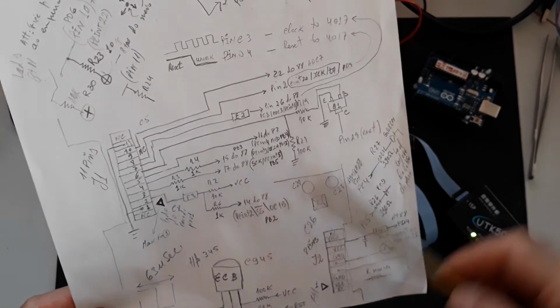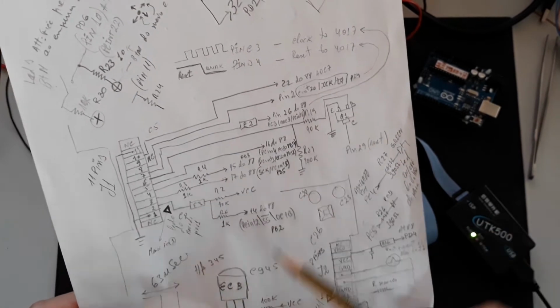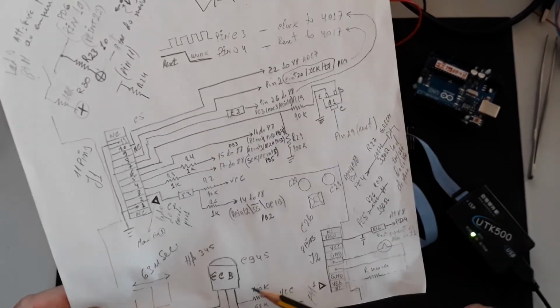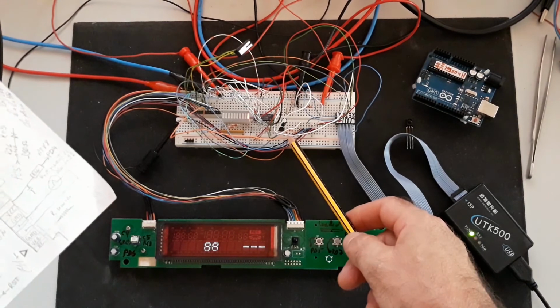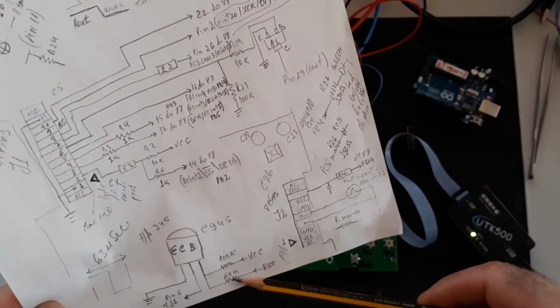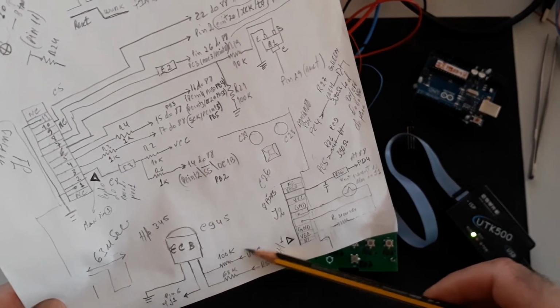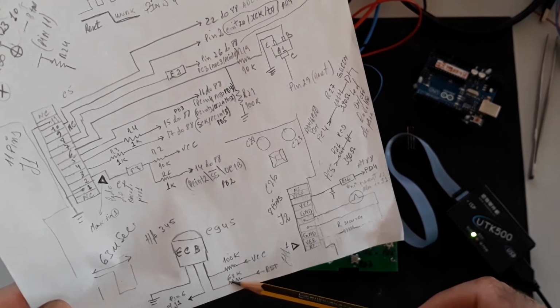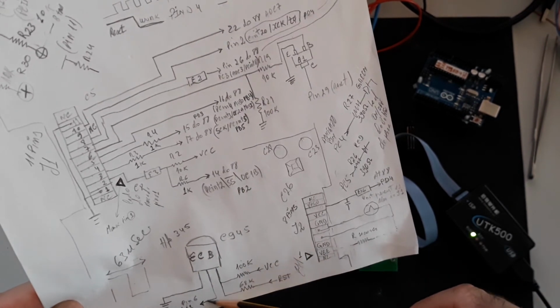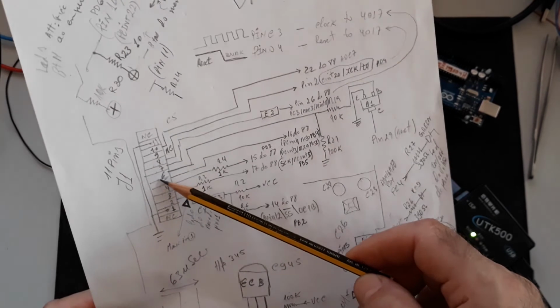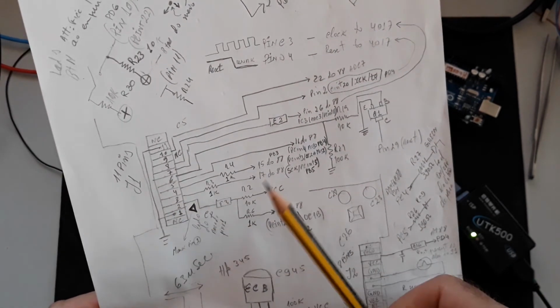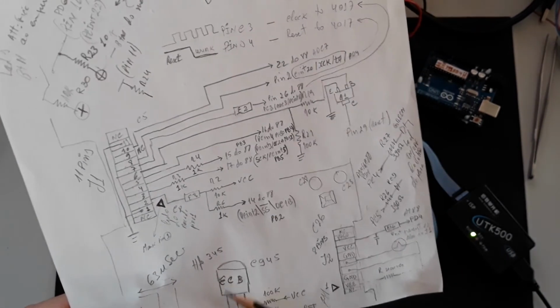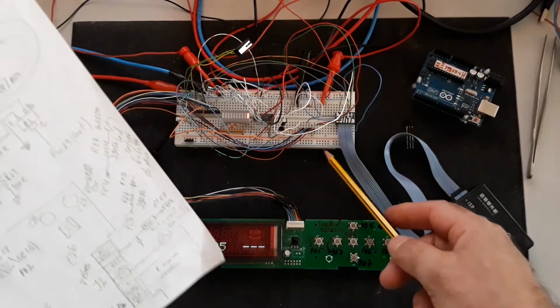These are important things you need to take care of, but it's very easy to implement, okay? This is implemented here on a proto board, okay? It receives the signal, has a pull up to the base, receives the negative signal in this case, and the collector goes to pin 6 of my connector, and the emitter is connected to the GND of the proto board, okay.